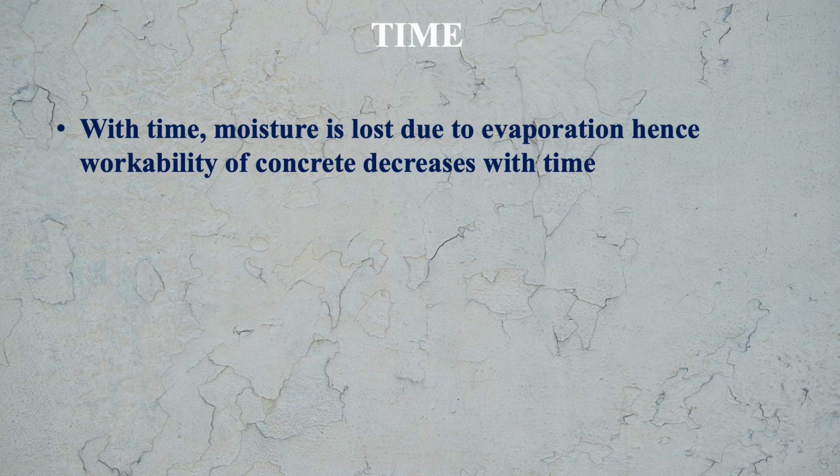Let us see the effect of time. As you know that once you have prepared the concrete, then what will happen with time? Moisture will be lost due to the evaporation. Hence, workability of concrete will decrease with time because less water will be available due to evaporation basically. So that way decrease in the workability will occur with time.